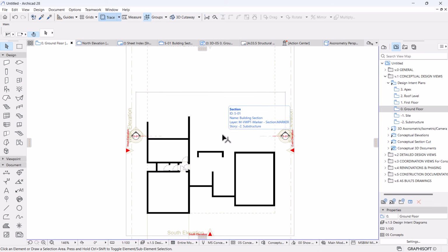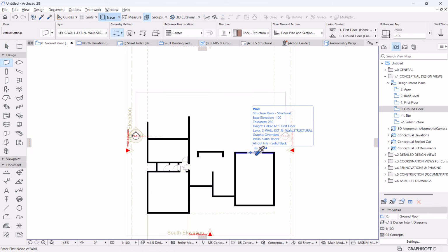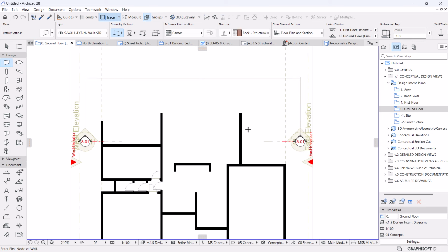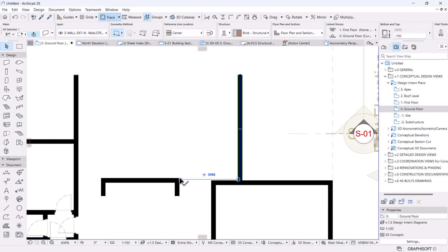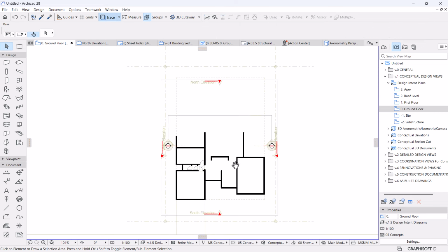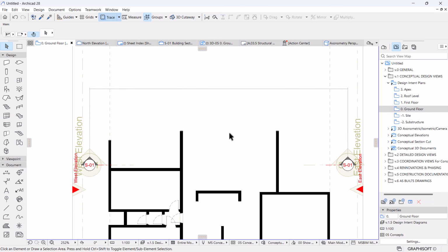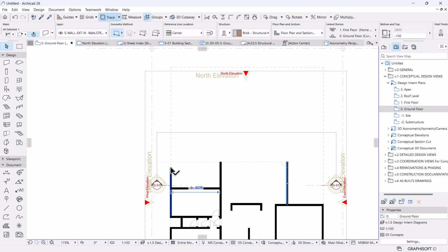So let's do that. I'm going to pick this wall. I'm going to draw a straight wall all the way to there. For now, this wall from here, I don't know why it's picking this wall. I thought it would pick this one, but you can adjust your guides by clicking on the arrow, then bring it to here. So now I want this to be 1.5. Okay, so 1.5 is pretty much cool. This will be the area for our dining, so the kitchen will be covered.